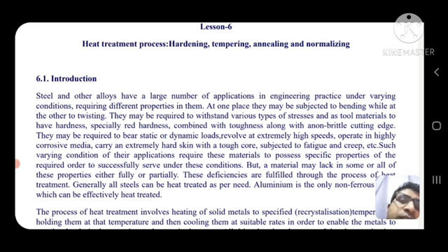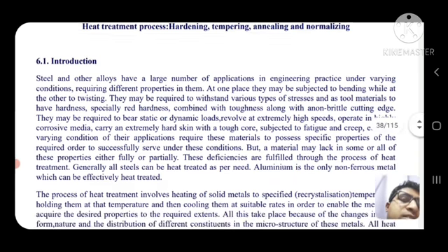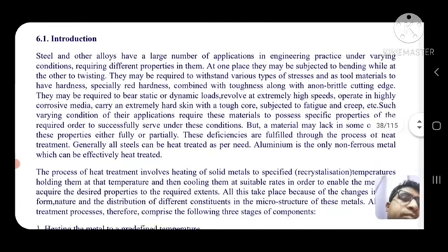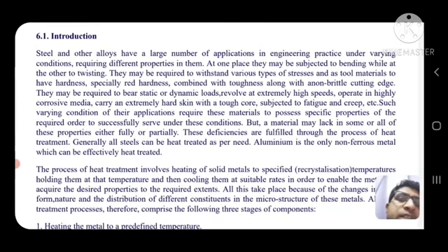At one place, they may be subjected to bending, while at another to twisting. They may be required to withstand various types of stress and, as tool material, to have hardness, especially red hardness, combined with toughness along with a non-brittle cutting edge.